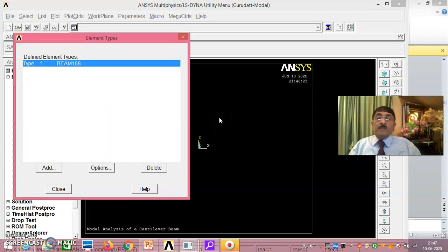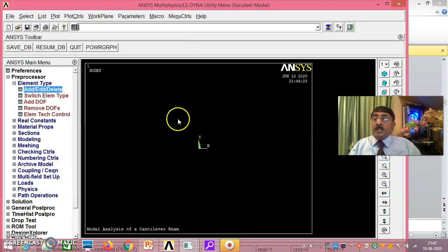Okay, what you've done in beams, the same element I'm choosing. Just say close. Beam 188 element you choose. Beam 188 element does not ask for real constant. Did you follow? You need directly the properties of this.